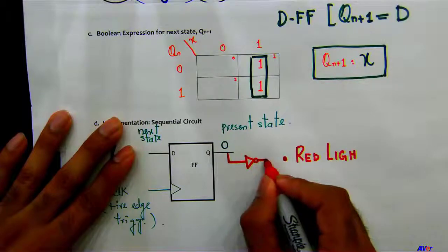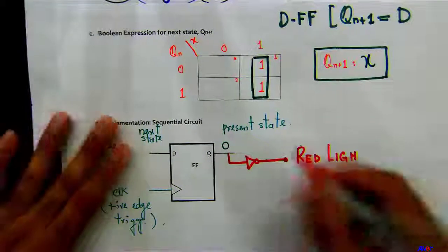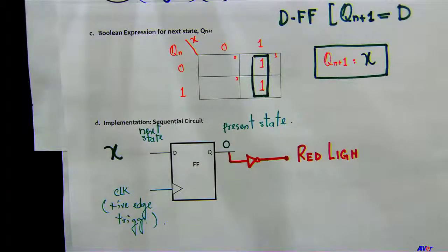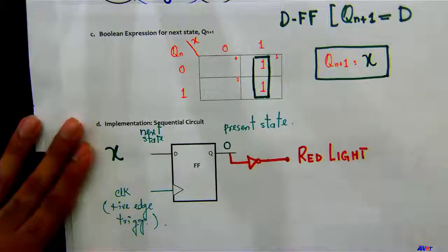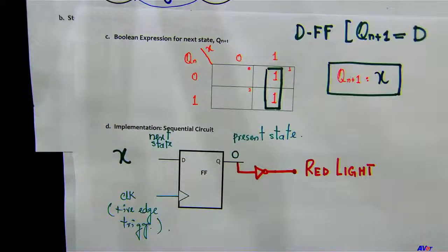Okay, and then obviously you're going to have the resistor, 2.2K. Or does anyone know how much voltage the red light needs in order to light up? Anybody who's taking 2019? No? It's 1.8. Okay, all right, and we know mostly we give 3.3 and 5 volts, so it's going to work. So you just need a resistor in series with that.